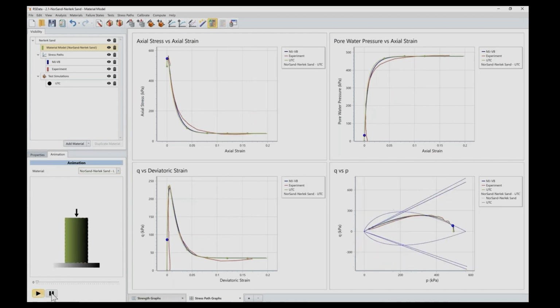So let me pause for a second. Initially, the yield surface of this constitutive model is a Cam-Clay. Originally, it looks like a bullet shape of Cam-Clay. Modified Cam-Clay was an ellipse. This one is bullet shape, and let me animate it again.